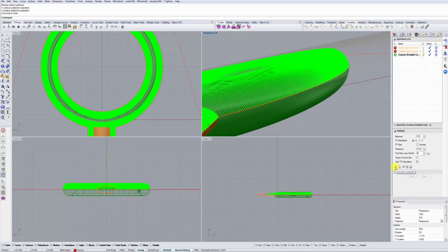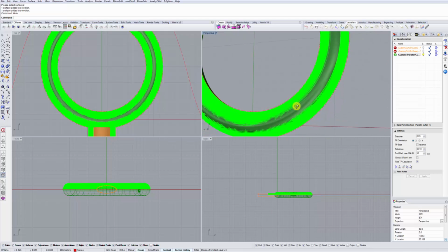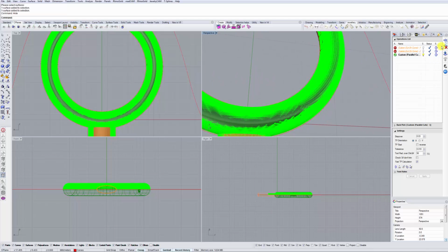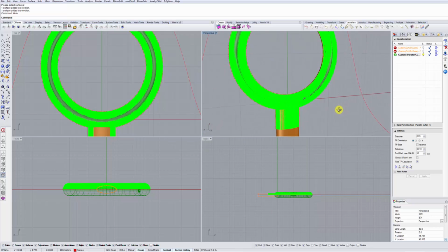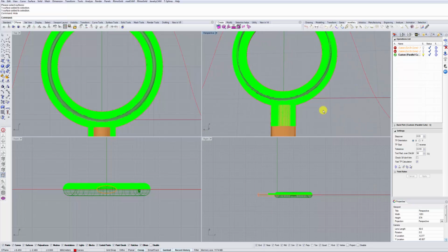We have our calculate toolpath option, change the view plane, change machining direction, and change the boundary curves. All of these buttons allow you to change the initial parameters that you specified when calculating this toolpath, so that you do not have to go to a new operation and redo certain steps. Now let's complete this by going to a different direction, this side, the opposite direction, and performing a similar operation.